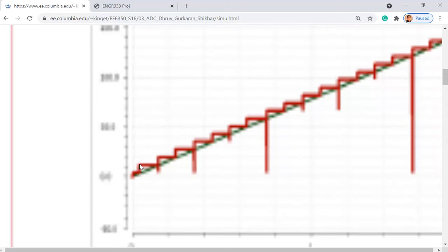Yeah, I think at the rising edge here, right? I haven't done that yet. I'm just thinking, whatever you think is right, we should do it. So remember when we were doing the hand calculation for the DNL and INL, we're just looking at the points of the input, and then see what the real step is over here. That's for DNL. For INL, you are looking at the absolute value of these points, right? I mean, it's doable, right? You just need to know how to load the raw data into MATLAB.